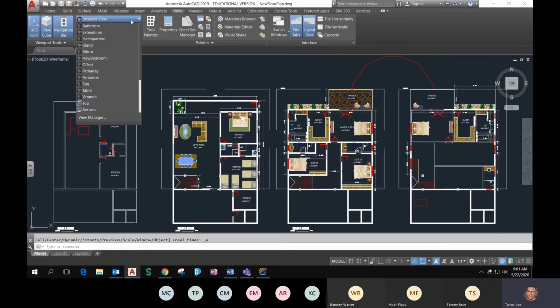Imagine a map in AutoCAD of the United States of America. That would be very large, wouldn't it? You could make a named view for each state. That way you wouldn't have to roll the wheel in every time or zoom around with the mouse to zoom in on Rhode Island or Vermont. You know, those are pretty small states. And so what you could do is you could save those views, click on the named view named Vermont, and it would zoom you right into that area, okay? But that's something that you make.